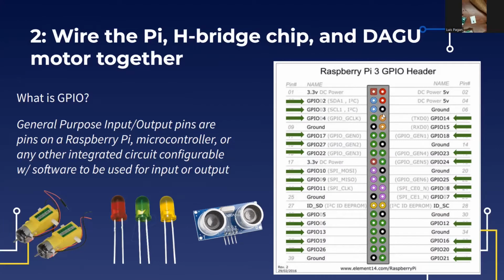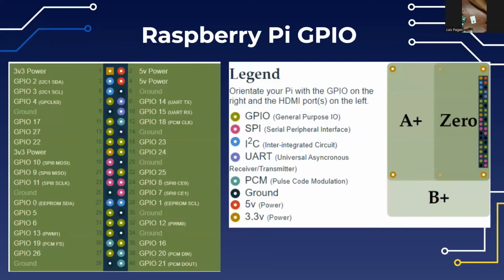And then we have a bunch of different GPIO pins. The ones that don't have any additional text are just digital pins. The other ones are also technically digital pins, but there are several that have PWM functionality, which is what we're going to be using to simulate an analog signal output. This gives you a better idea.